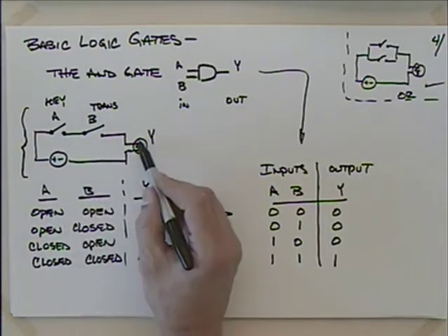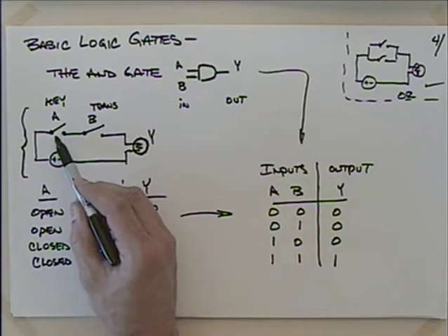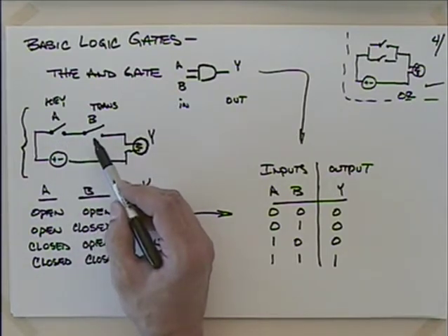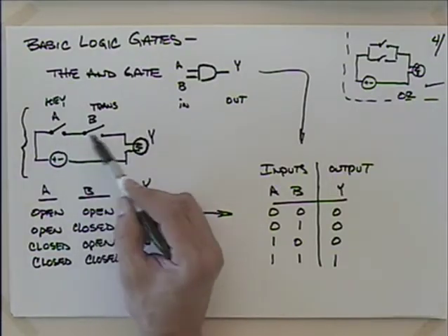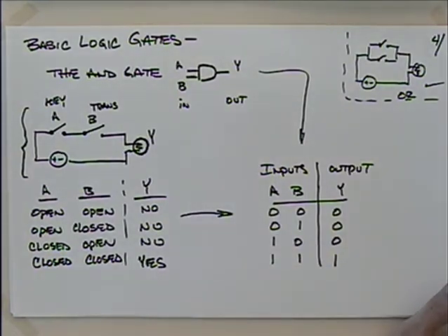Before your furnace can start up, we probably want to make sure that the draft inducer is working. We probably want to make sure that the temperature is not too high. We would have several checks, and all of those checks would have to be closed for that to work out, right? Okay. So logically speaking, I don't think this is too big of a deal.